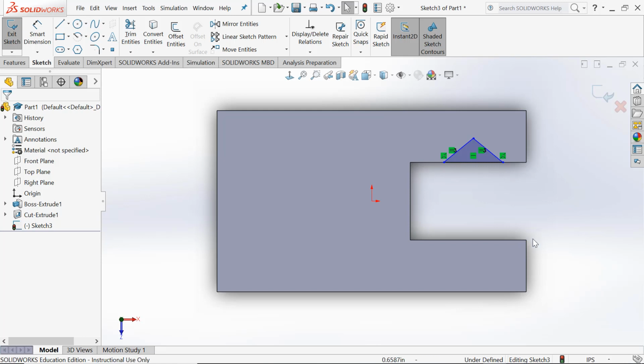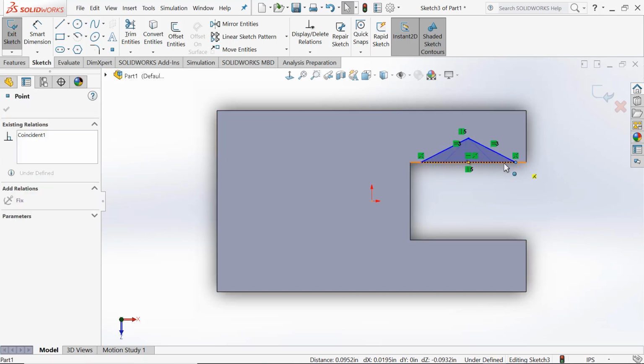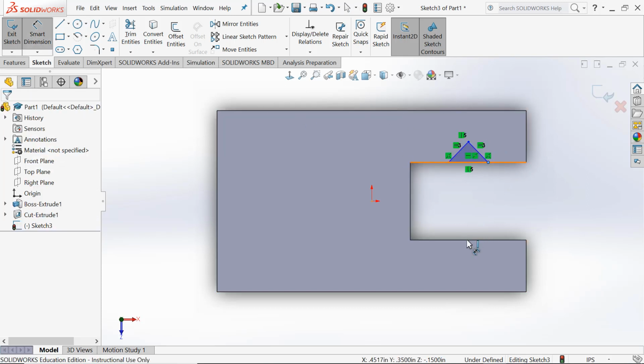So what you're going to want to do is click either this line or that line. It really doesn't matter which. Right-click on it, select midpoint. Hold down the Shift button, click on this point here, make those two vertical, and now you can see that's going to remain centered on here. I can dimension the depth of it, and I can dimension the width of it, but it's always going to stay there. I don't know what the depth of it really is, and I think it's probably given in this way. No, not that. Make sure I can escape until those are unselected.